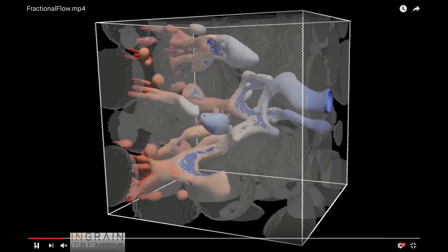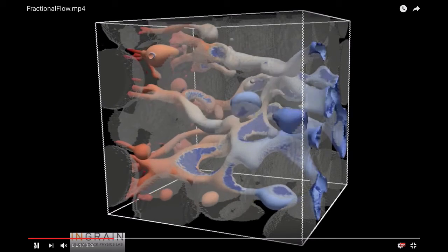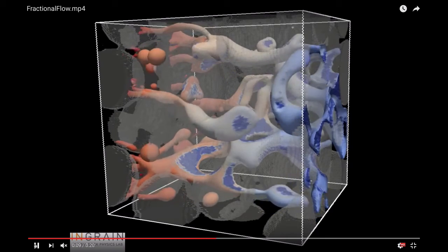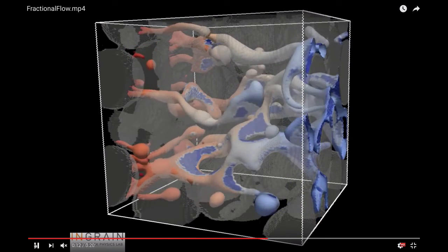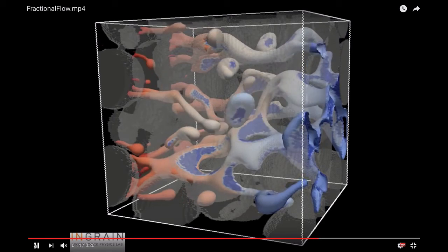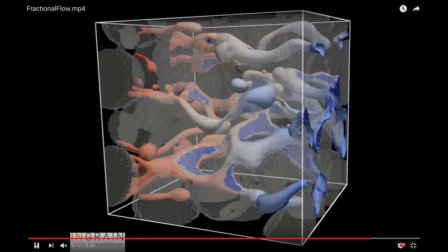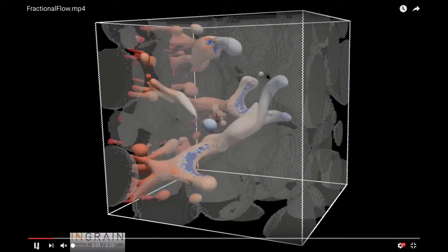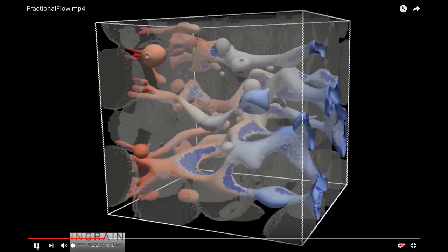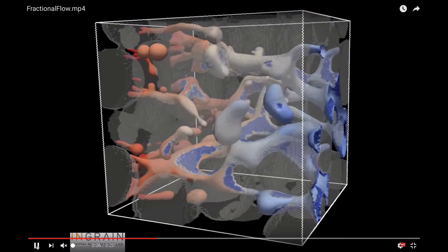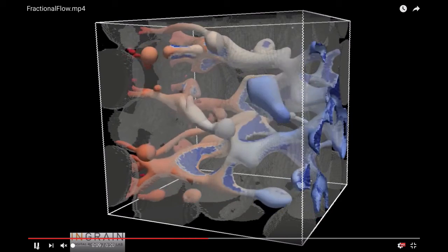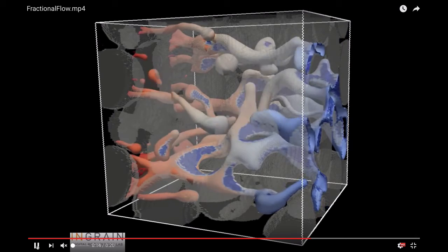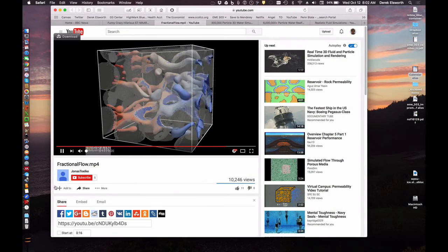And so if you throw away the momentum equations, then what you have to do is incorporate these frictional losses within the system, which are what this term that we called H sub L, or losses, in our class last time. And so we'll end up putting together the equations that allow us to solve these problems, which, as I say, you'll see in the rest of your career here, because it's basically the essence of reservoir engineering: being able to solve for problems like this. How much fluid do you get through the system if you try sucking it out? Basically the question. And so that's where we'll ultimately go today.